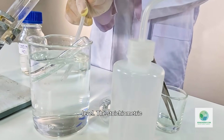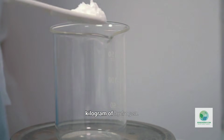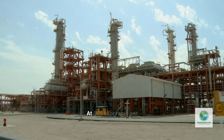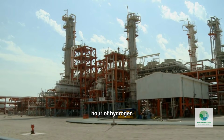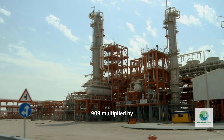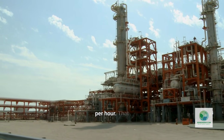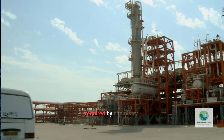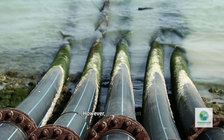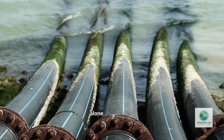The stoichiometric requirement for electrolysis is 9 kilograms of water per kilogram of hydrogen. At 909 kilograms per hour of hydrogen production, the theoretical water requirement is 909 multiplied by 9, which equals 8.18 cubic meters per hour. That is the minimum required by chemistry. However, practical plant operation requires more water than stoichiometry alone.